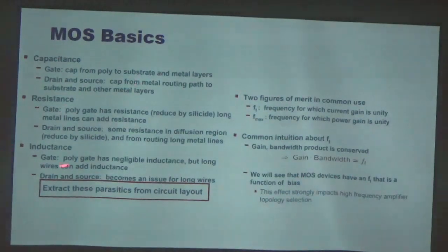So these are the capacitance, also there is some resistance, and when we go for the higher model of the gate, there are some inductance also we will find. So when you do the RFIC design, you need to take all these parasitics into your account, and then you will need to design, and then we extract all these parasitics from the layout.